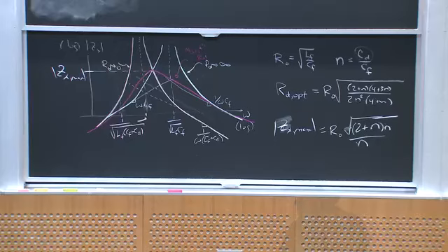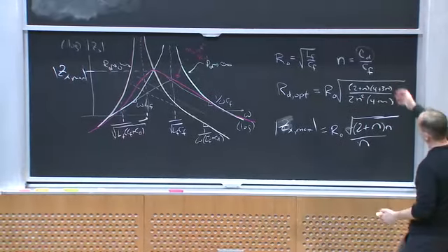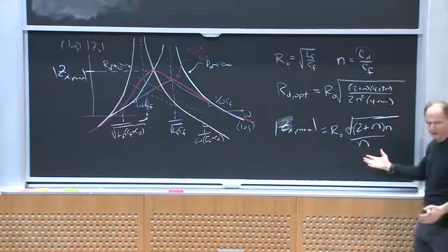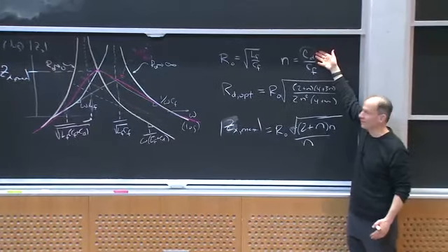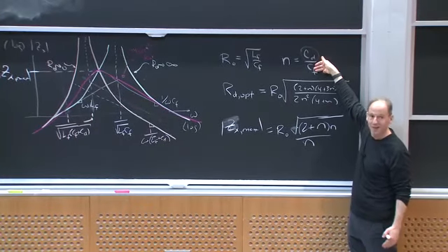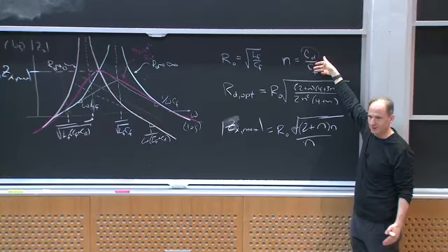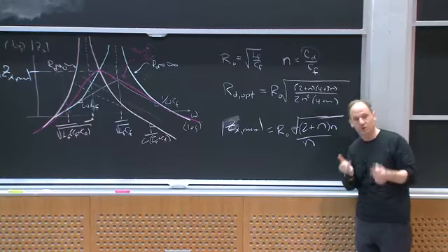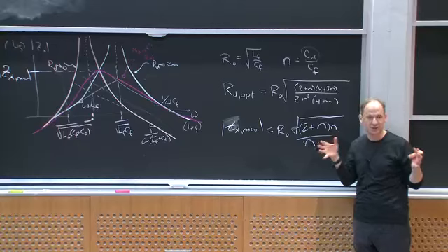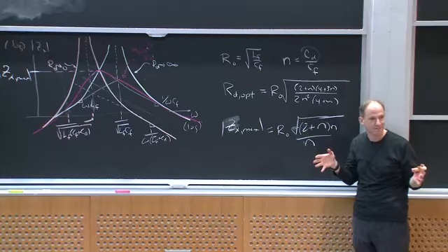Okay? Now the thing we don't like about doing this is you say, well, why don't I just make n really big, and then this will be really well damped? Well, the reason is I've got to pay for that capacitor, right? If I'm choosing CD as 10 times CF, that's expensive, in terms of cost, but also in terms of volume, because it has to store 10 times the energy of CF.